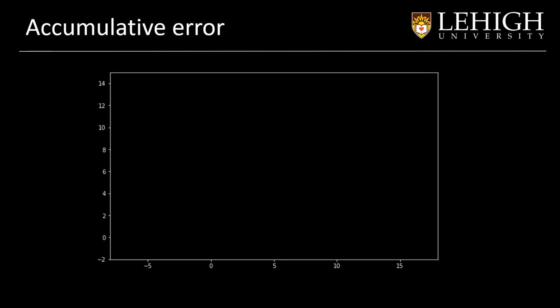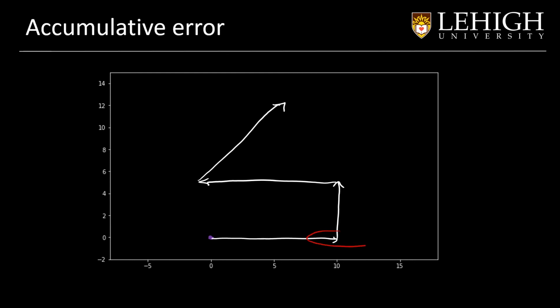The main problem of the odometry is that the error will be accumulating while we move. For example, if we start in this location and apply the following control inputs, what we are going to see in the end is that the error, for example for the drone, is very small in the y-axis, but when it breaks, the error can be higher.